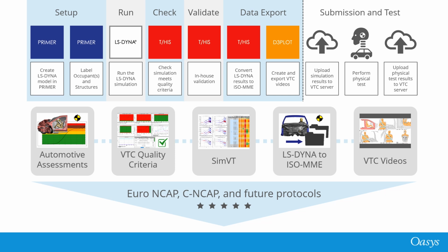Automotive assessments allows users to define workflow data once, making it easier to handle the increased volume of LS-DYNA analysis required for virtual testing. LS-DYNA to ISO-MME workflow automatically maps LS-DYNA entities to ISO-MME channel codes, which saves time and reduces human error. SimVT helps CAE teams monitor and meet the correlation requirements to validate their virtual test models. VTC Quality Criteria and videos help vehicle safety teams to create video files efficiently, ensuring the required format and quality.